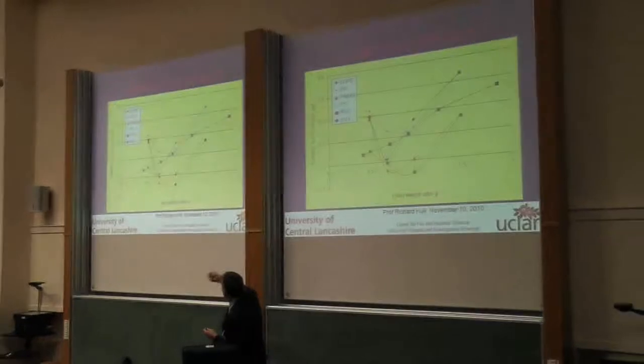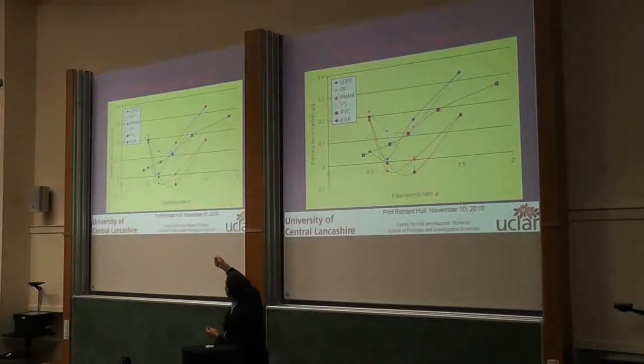But you can see in all cases we get much higher yields, maybe a third of the carbon comes out unburned, as you might expect when the equivalence ratio is 1.5. You didn't have enough oxygen there.